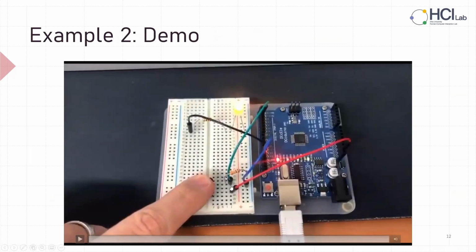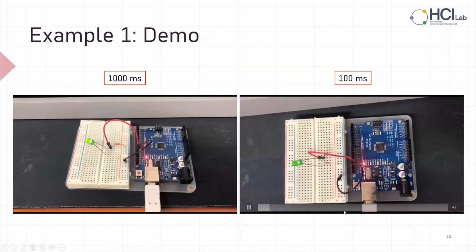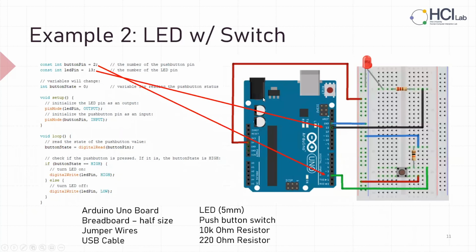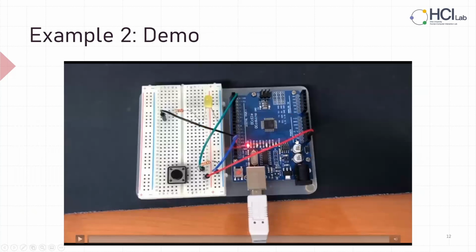As you can see, the connection is the same as in this picture, this example. Here our 5 volts comes to our pin, and we put a 10 kilo ohm resistor to ground. The blue wire is ground.